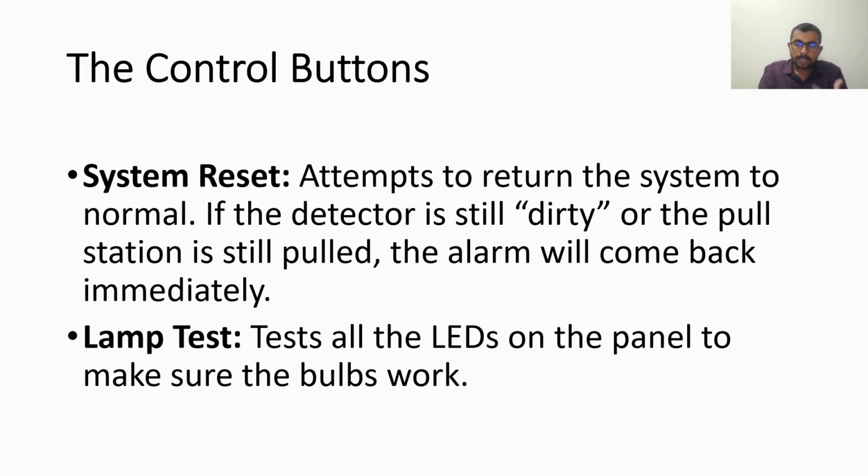Now, suppose the detector is dirty or the pull station is still kept in activated mode, that is, if the pull station is not reset, then the alarm will come back again immediately. So it is necessary that the fault or the alarm origin is rectified. Then we can make sure that the panel is kept normal.